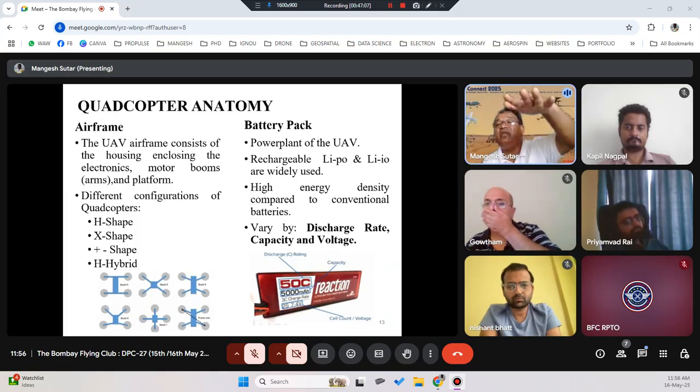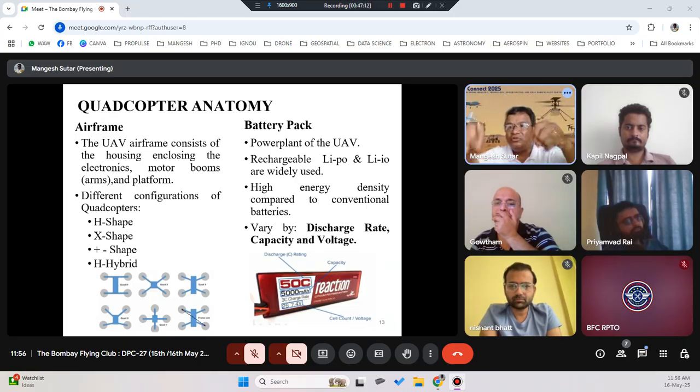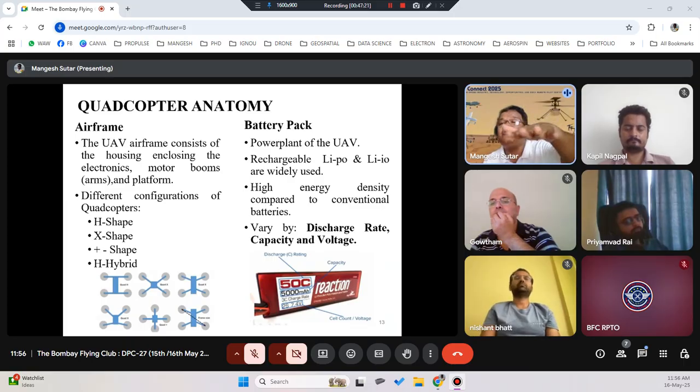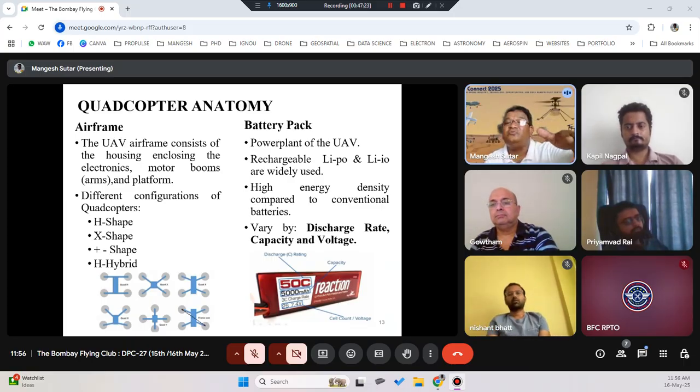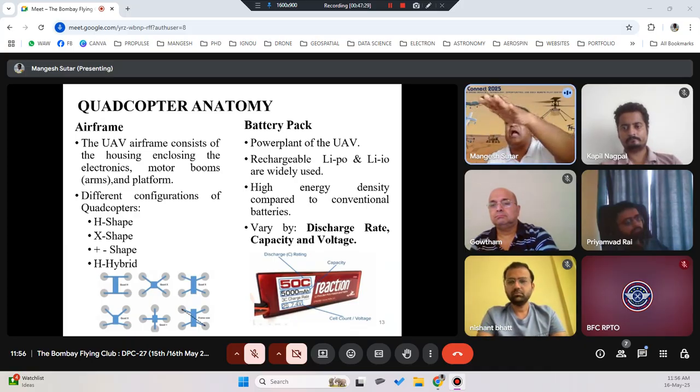So initially it may be 24 kg, but as it is functioning its purpose, it is putting the fertilizer on the crops, and its weight will start reducing. So in every scenario, from the highest weight, that is 24 kg, till it comes to, let's say, 14 kg, within that range the drone has to be stable. Without the fertilizer tank being loaded, and with the fertilizer tank 100% loaded, the drone has to perform at the same level. Okay, so that is how you design your airframe, based on your requirement.